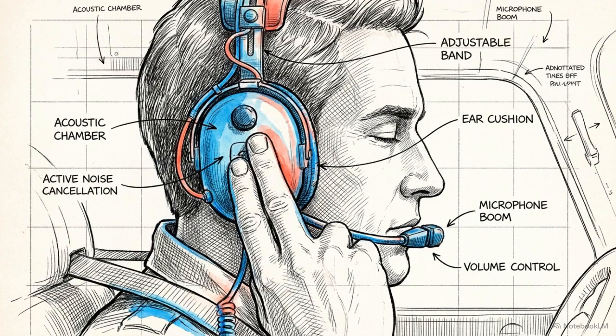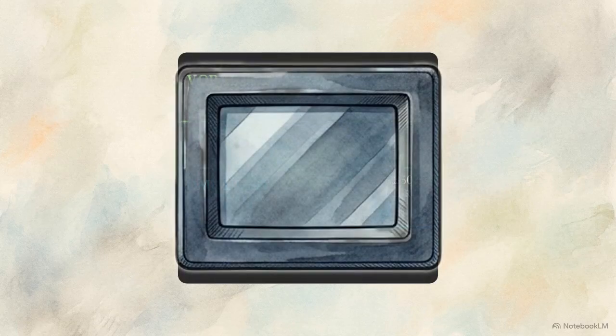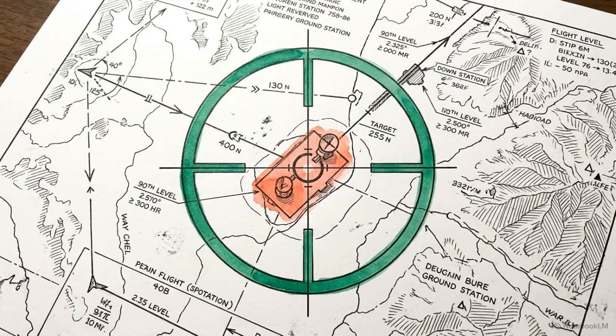This audio waveform visualization isolates how the paired signals broadcast their Morse code identifiers. The top half shows the VOR broadcasting at 1020 Hz every 10 seconds. The bottom half shows the paired DME broadcasting at a higher 1350 Hz pitch just once every 30 seconds. Isolating this specific high-pitched 30-second audio pulse guarantees that the pilot's spatial geometry is locked on to the correct ground target.